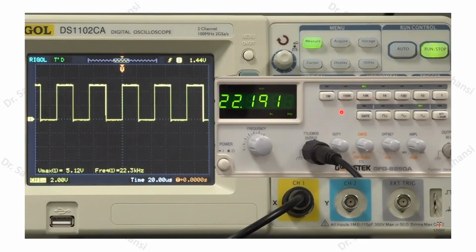This is your waveform generator actually. And from the waveform generator, you have to connect this to a particular circuit, at the clock input, I mean to say. There you have to apply a clock pulse of a certain frequency and of a certain duty cycle. You can control the duty cycle by having a duty cycle knob.